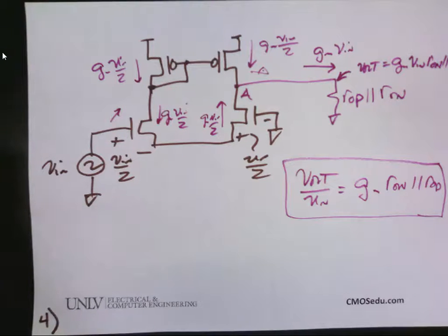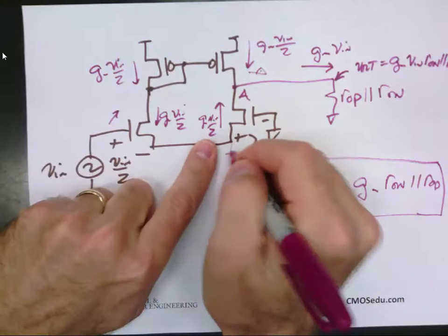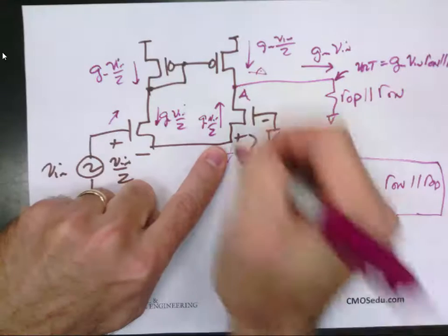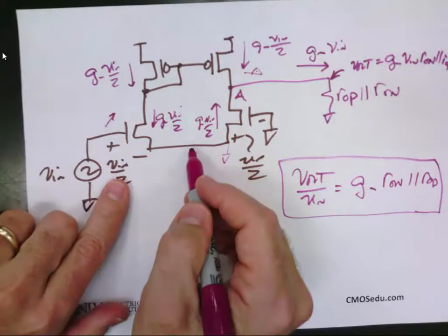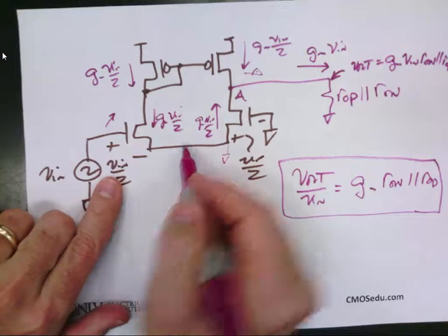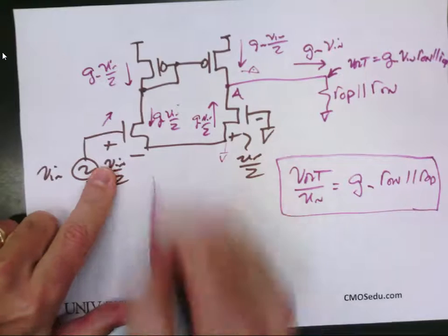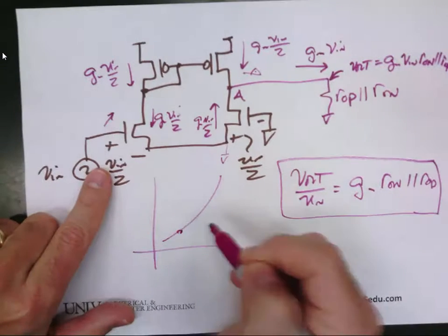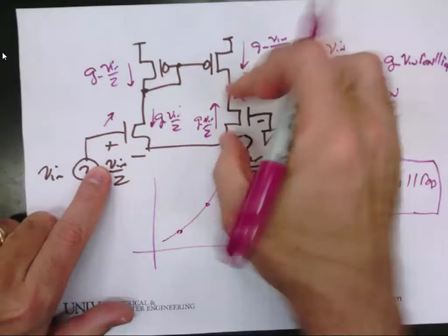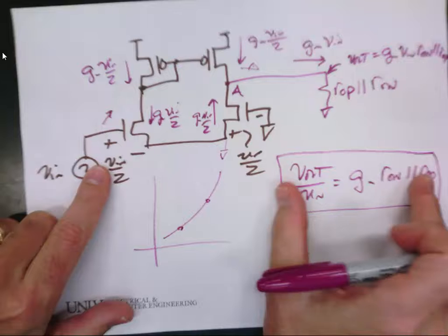Why is it what? The resistance looking down in here. If this was ground, then that would be precisely RON, right? But it's not ground, it's a low impedance, so I'm approximating the resistance looking down is RON. Remember, I don't want to be too academic because my RON does this. So I say, oh, it's this value, but then I have actually a larger VDS, it moves up here. Any questions?